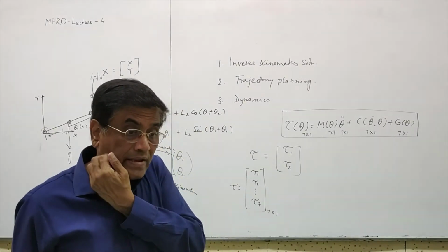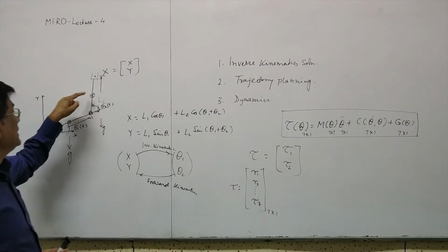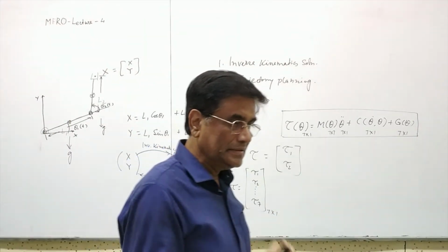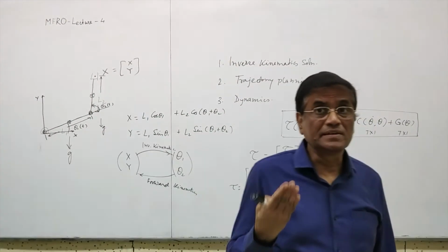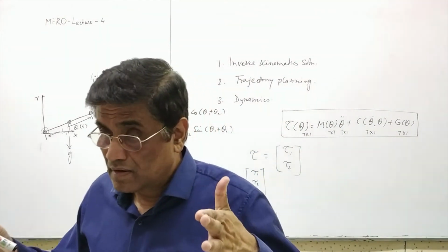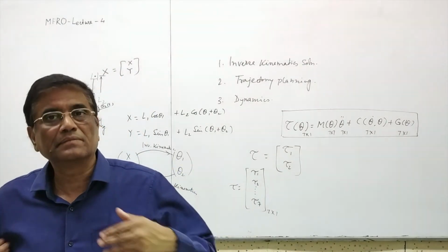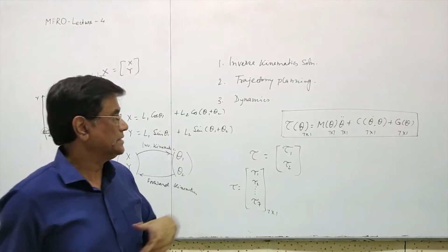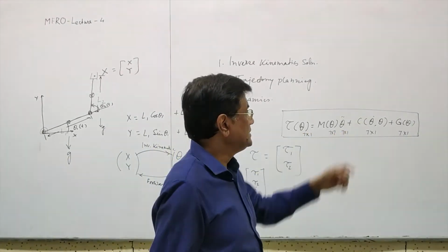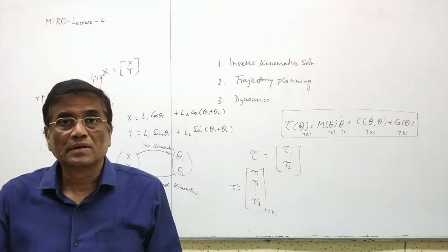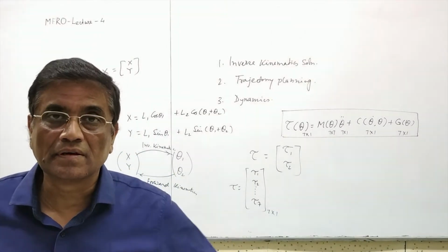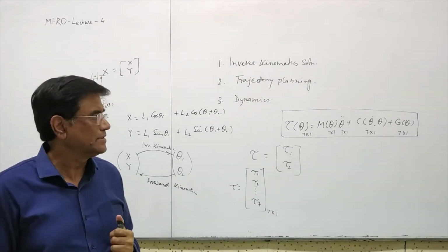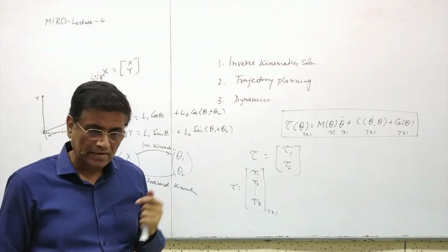And there is another term when there are two relative motions. Coriolis force comes into existence. They may be small, but they are significant when you have a robot having substantial mass and moving with a substantial velocity, right? So these are significant at that time. Coriolis is actually the effect of mutual relative motions, right? I can give an example. You can see the Coriolis effect in many applications.